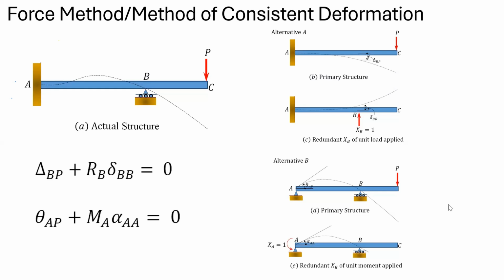And how many equilibrium equations do we have? We have only 2 equilibrium equations, that is summation Fy = 0 and summation M = 0. So 3 minus 2 is 1. So DS is 1. DS 1 means what? It is a statically indeterminate structure. The first degree, the very first structure, that is the propped cantilever. The propped cantilever is the first degree of statically indeterminate structure.